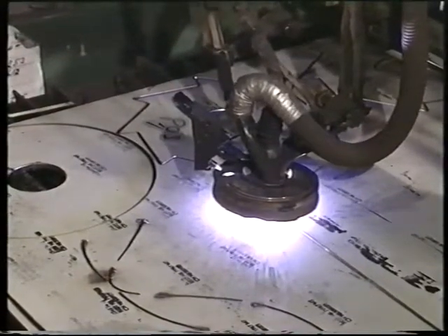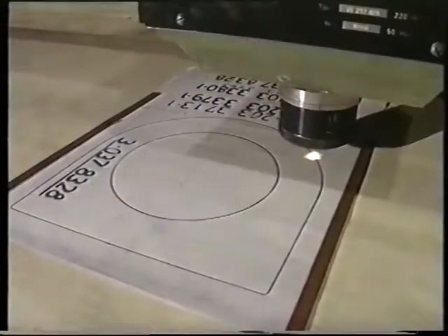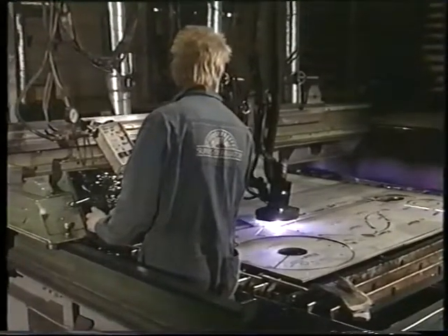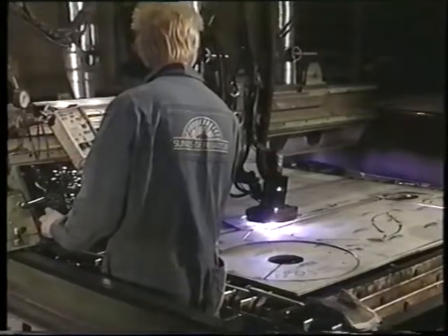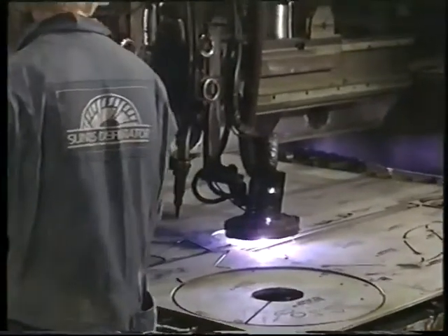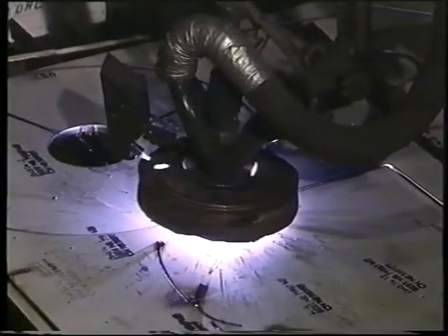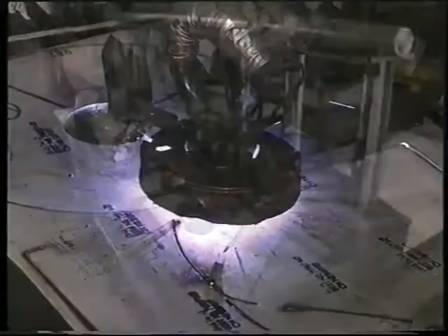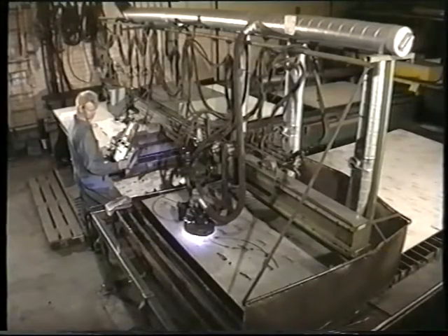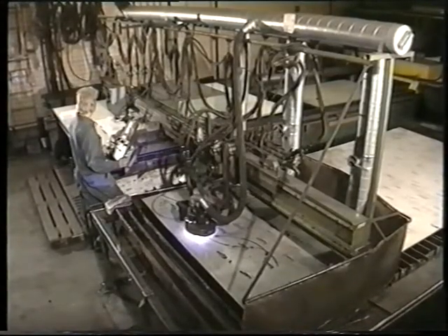It uses an L-Tech power source. Plate utilization is today 60%, but with the aid of computerized nesting, this figure can be raised to 80% in the future. This means a payback time for the computers, etc., of only a few months, since the average cost for the material cut in this shop is very high.